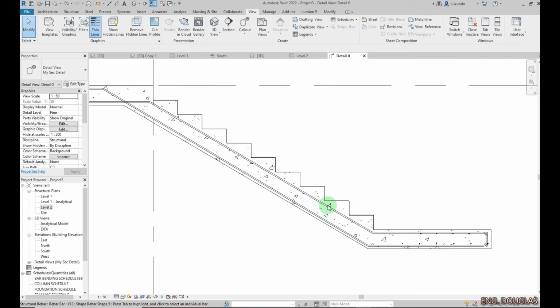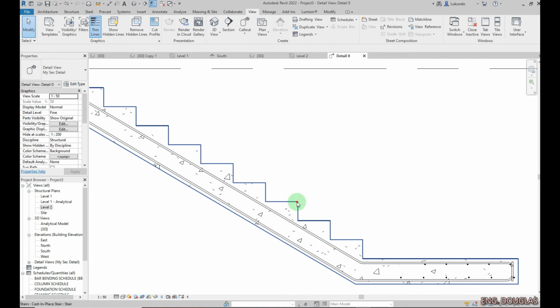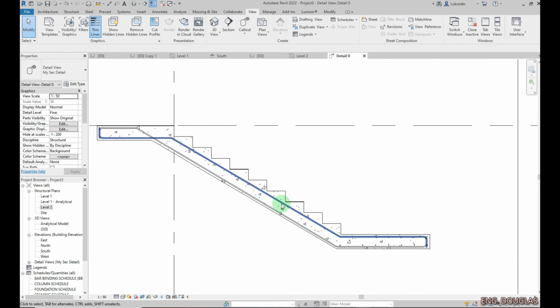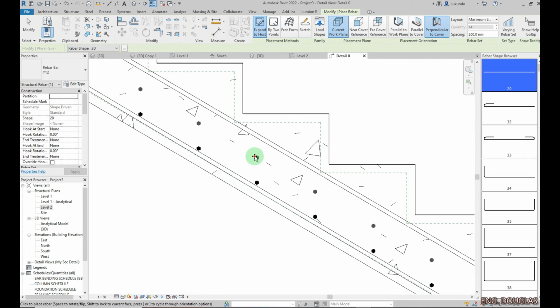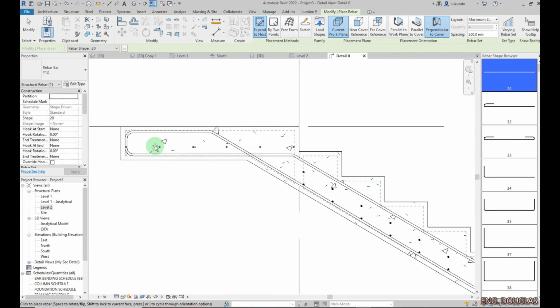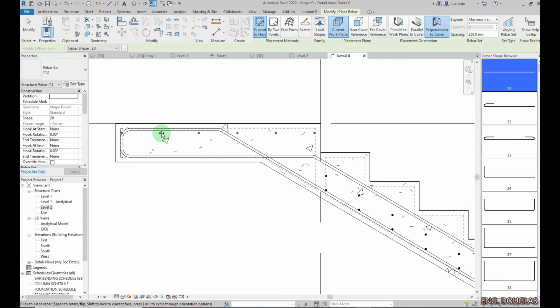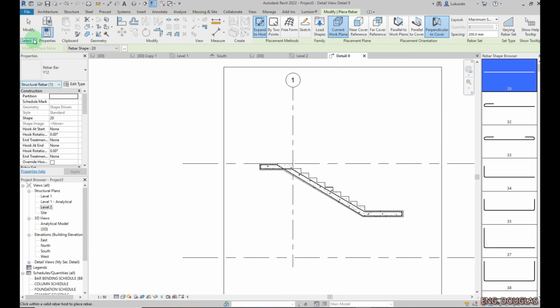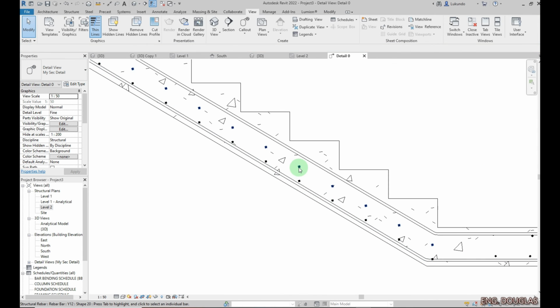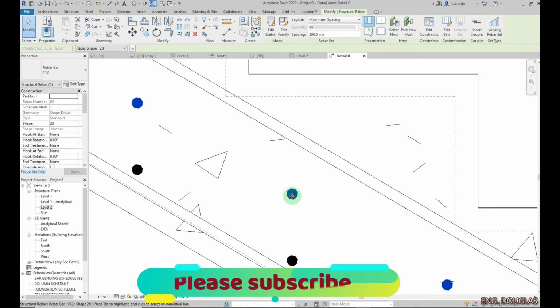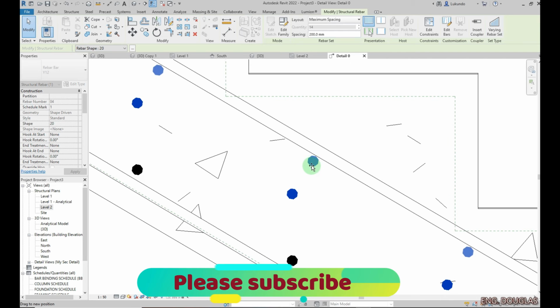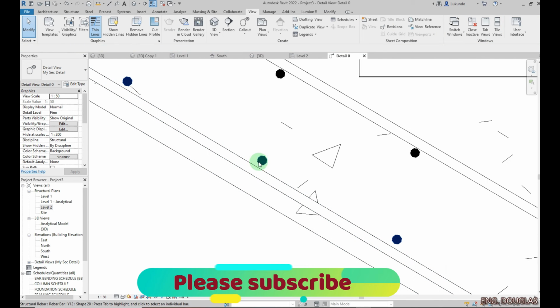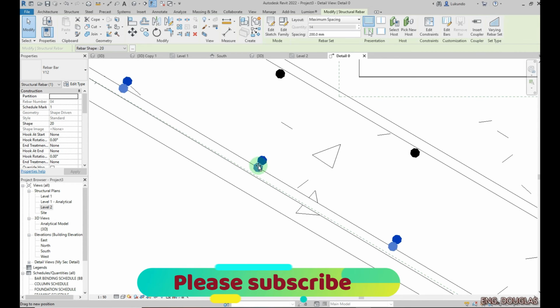We want to have the rebar in the other direction, because this is doubly reinforced. Then on top, I'll just place it there or move it later on. Then go there. You have the rebar right there and down there up to somewhere there. Then click on modify. Once you do that, you can simply pick the rebar and hold my left mouse and just drag it close there. If you want, again, you can select the bar if you want to lock it, and that's a good practice. You have to be doing that.